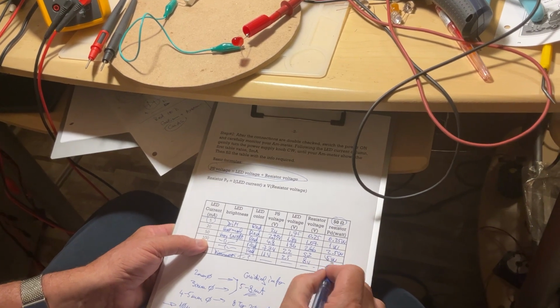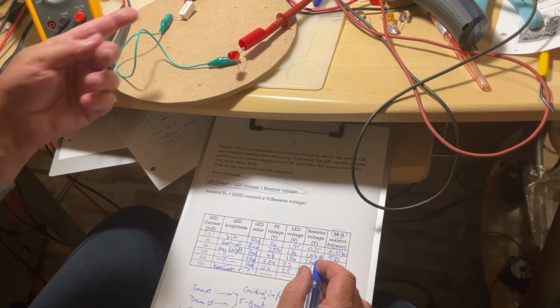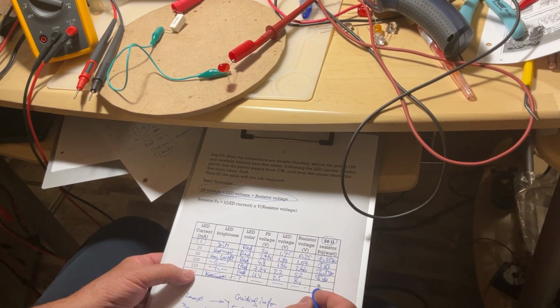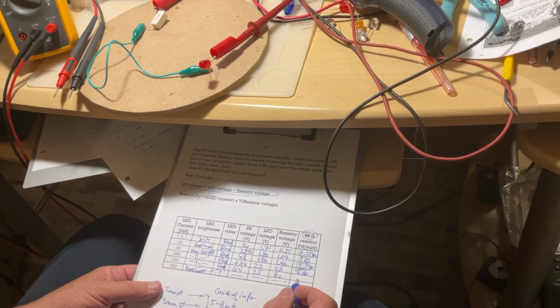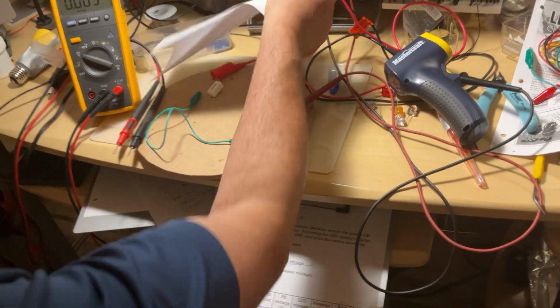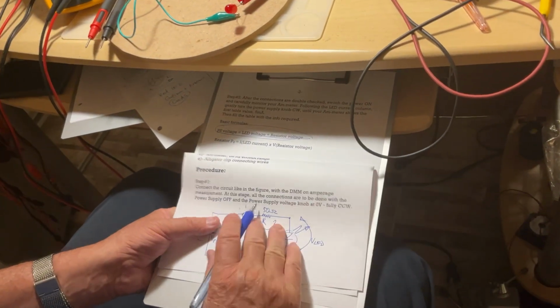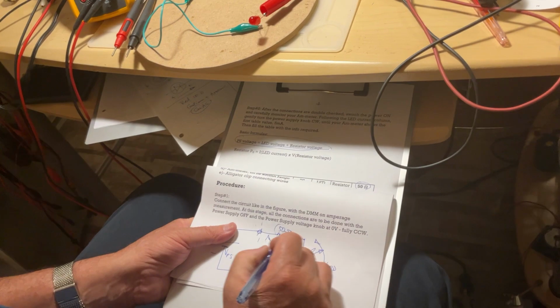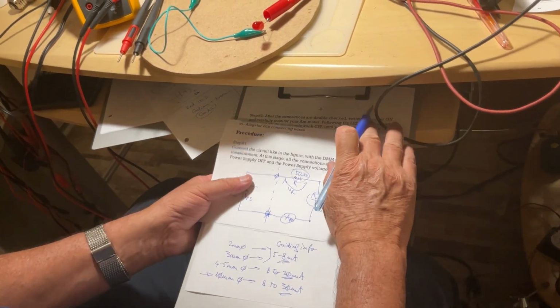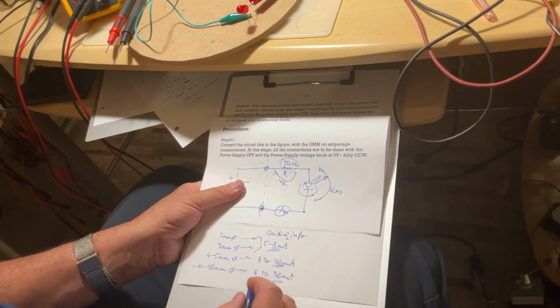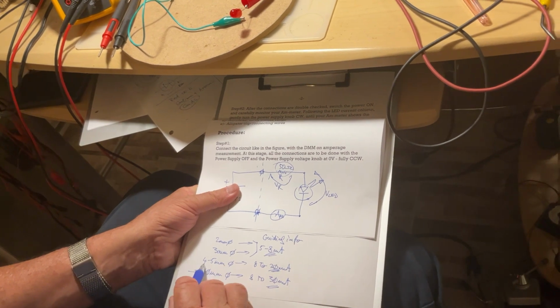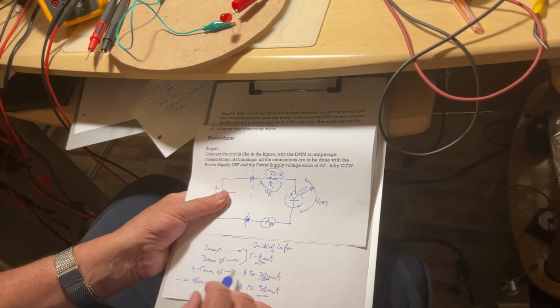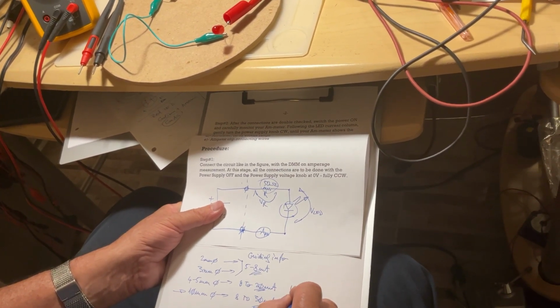So you see, we did not exceed the maximum power of the resistor, but if we hold this for a longer time at higher amperage, the resistor is going to heat up. So that's the thing about the circuit where you connect a diode. Not only do you have to provide a limiting resistor, whose purpose is to maintain the maximum recommended amperage through the diode. Example, if I want to energize a 4 to 5 millimeter diode, the current is going to be anywhere between 8 to 20 milliamps. I would recommend, let's say, 10 milliamps.